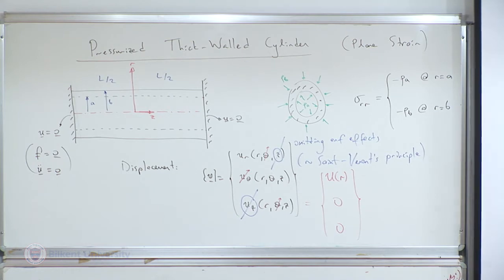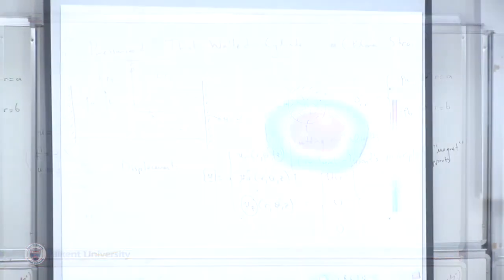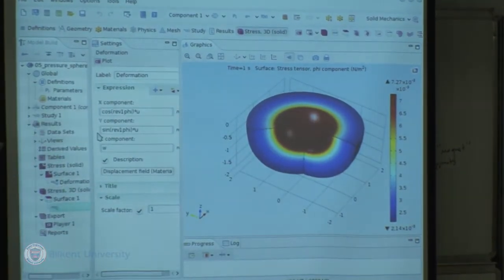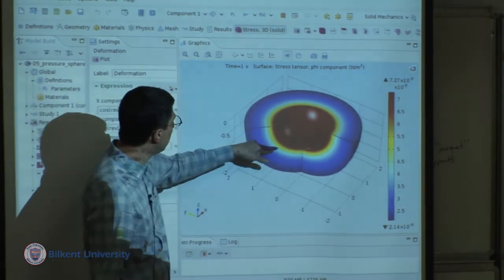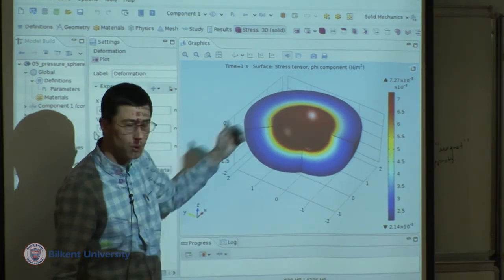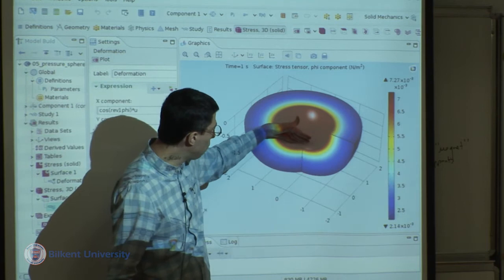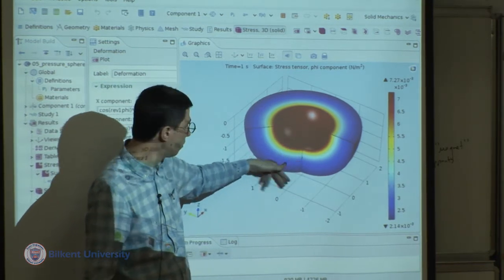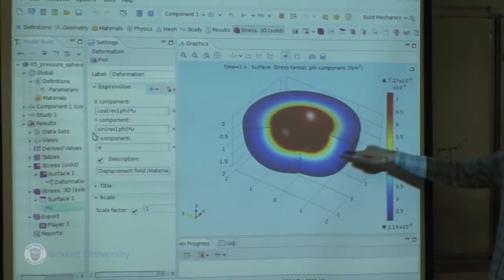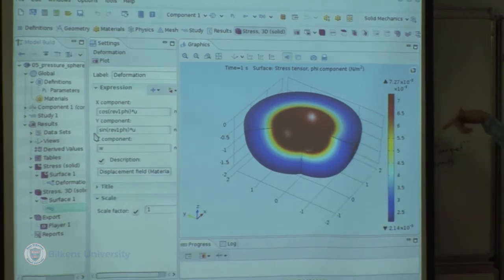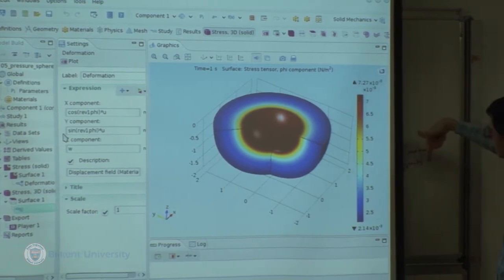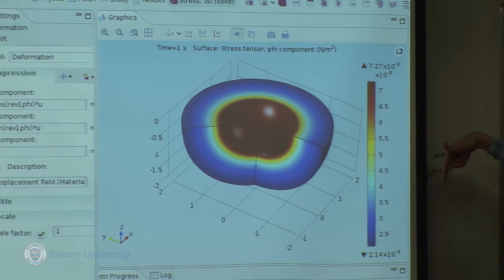Before I do that, let me show you a numerical example that demonstrates these points I was talking about. That's the solution. We've already solved for it. I'm showing only half of it, and 1/4 of it is chopped off. What you're looking at here, for a given pressure, is the angular stress, the tangential stress that we solved for. And we know that the tangential stress varies for the thick-walled case. It's not a constant. It varies considerably. Perhaps only relative magnitudes are important. Along the radial position, the stress has a decreasing tendency, both for the radial and the tangential components.